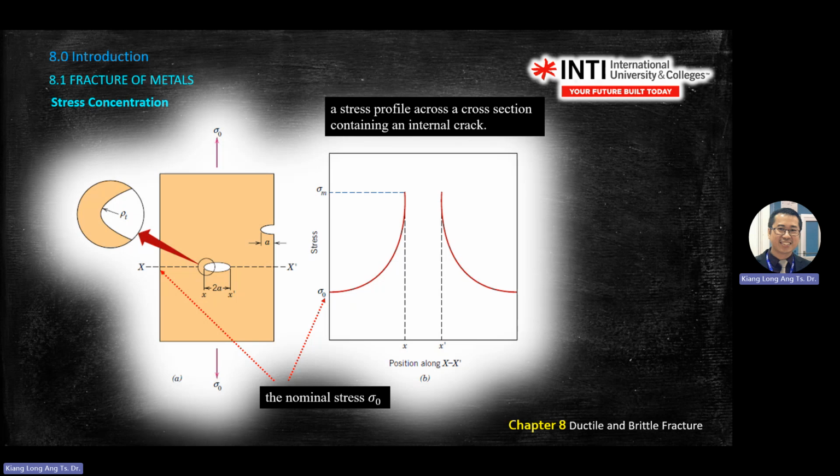One at the side, which means there is a stress concentrator at the side. Either the question gives you the problem from the side, or from the inner. There is a cavity, and the cavity is 2a. Remember, when you do the calculation for a cavity, you are calculating 2a and not a. You need to read the question carefully.